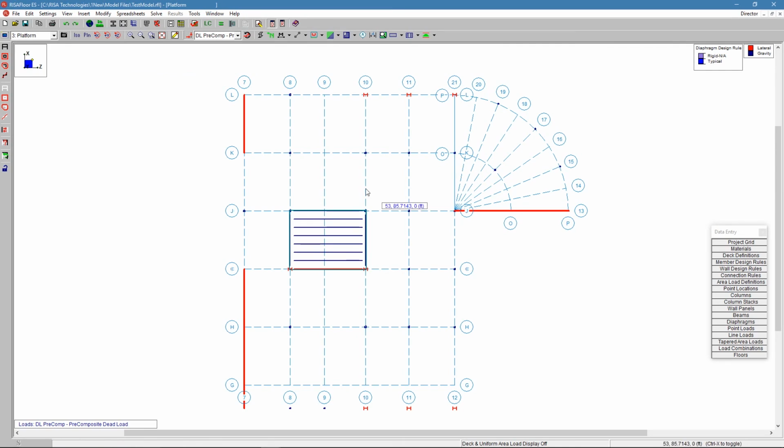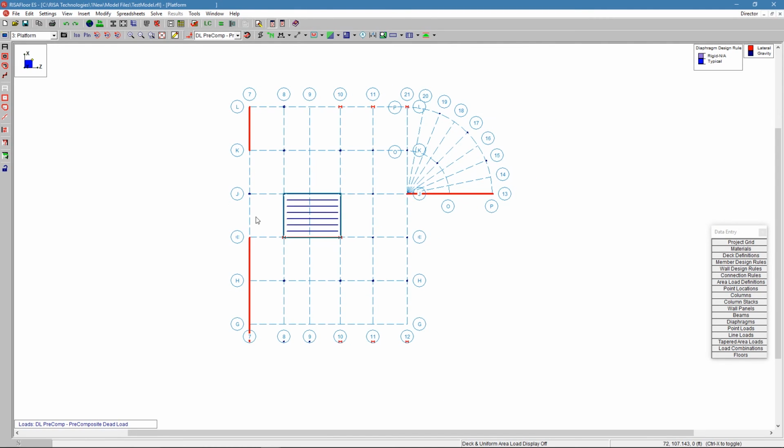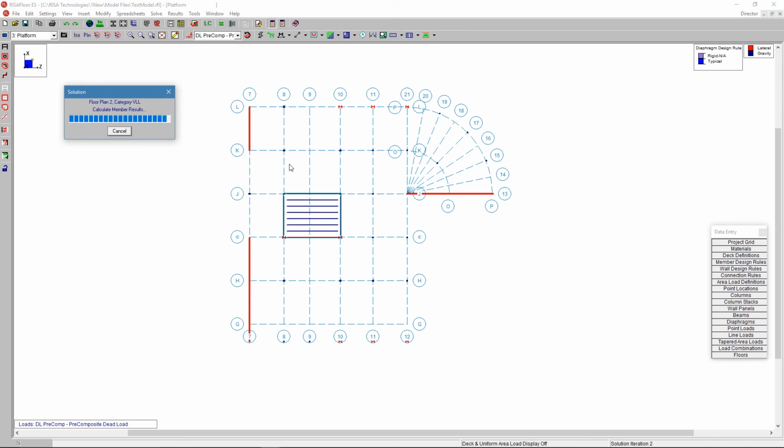So it's kind of like a clear button, clear all of the memory of that wall panel regions, and you're ready to go. So now, let's see here, I've gone through and I've run all of that information, so I'm just going to solve the model. It's going to calculate the loads down the structure, designing all of the gravity, again here in RISAFloor, doing all the gravity design, optimizing all of our shapes.